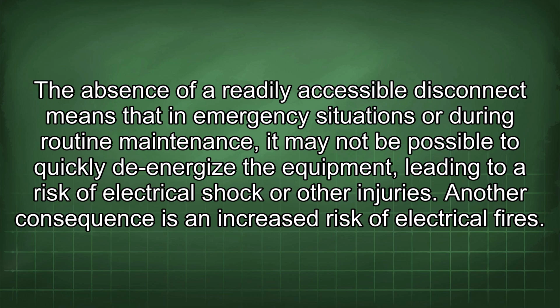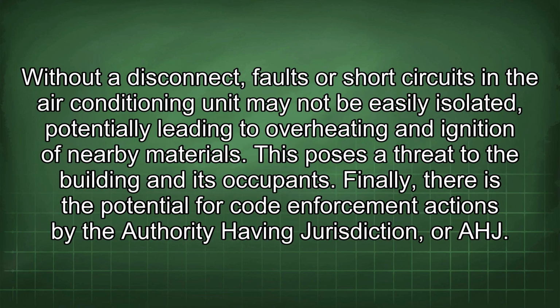Another consequence is an increased risk of electrical fires. Without a disconnect, faults or short circuits in the air conditioning unit may not be easily isolated, potentially leading to overheating and ignition of nearby materials. This poses a threat to the building and its occupants.